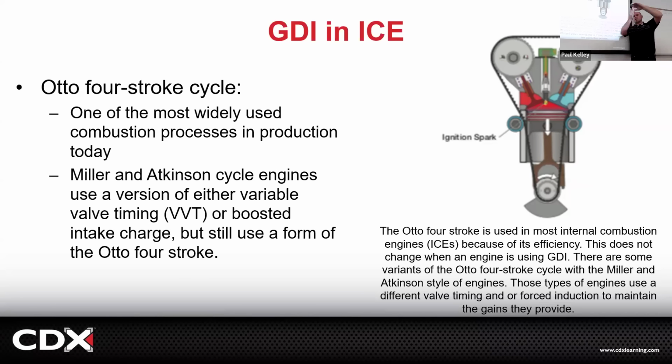If the piston went all the way down and then all the way up, that's 2 liters of displacement across 4 cylinders. Now instead, if we bring it down and leave the intake valve open, we push half of it out. If half of it's out, we essentially have a 1-liter. You get 1-liter fuel economy when you run it in this Atkinson cycle design.